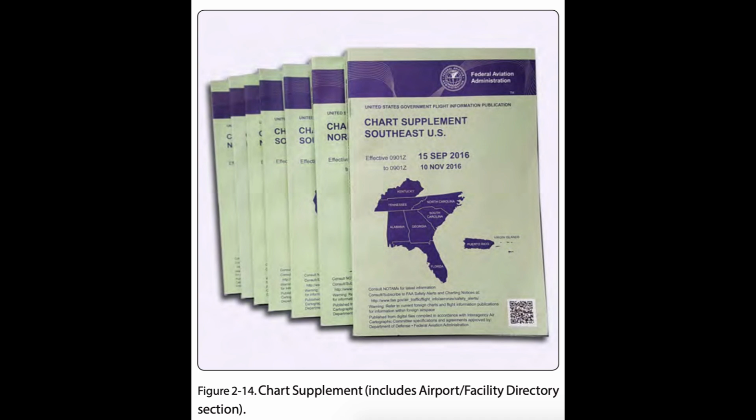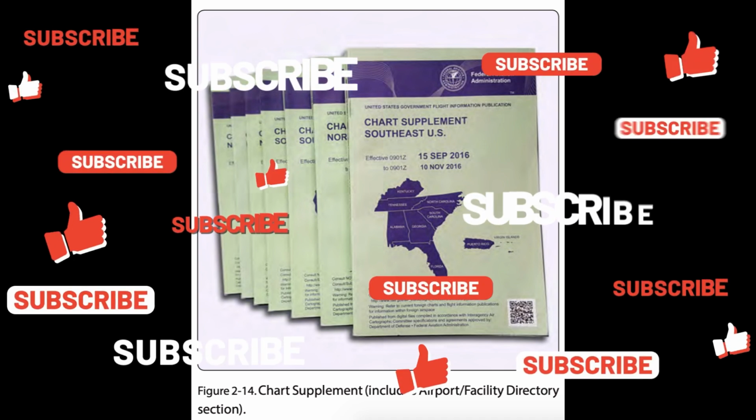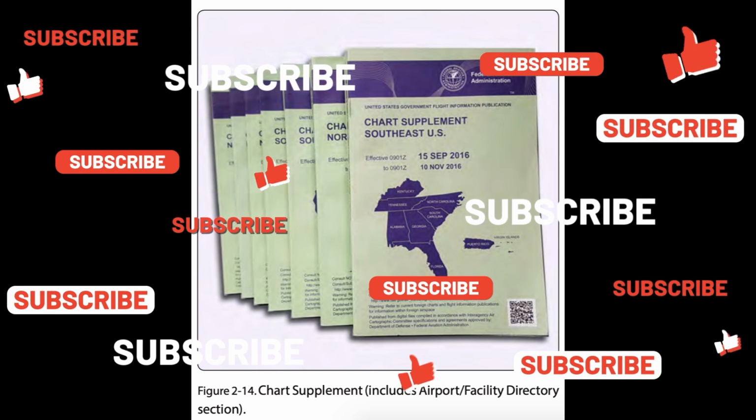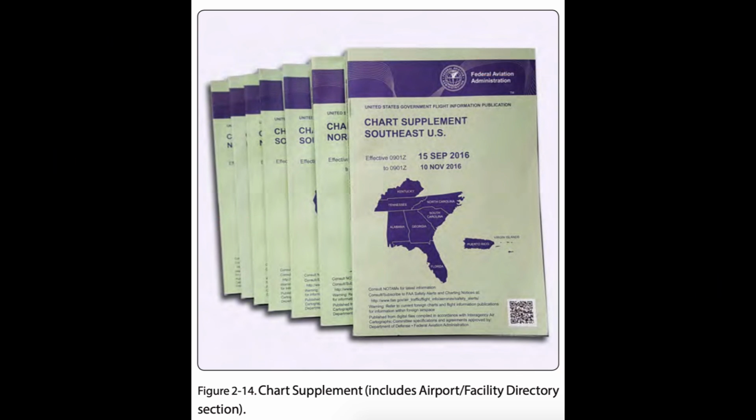Preferred IFR routes beginning or ending with a fix indicate that pilots may be routed to or from these fixes via a SID route, radar vectors, or a STAR. Routes for major terminals are listed alphabetically under the name of the departure airport. Where several airports are in proximity, they are listed under the principal airport and categorized as a metropolitan area, e.g., New York metro area. One-way preferred IFR routes are listed numerically, showing the segment fixes and the direction and times effective. Where more than one route is listed, the routes have equal priority for use.